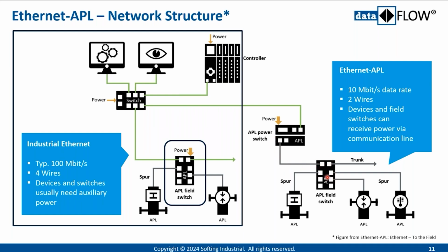The disadvantage with this one is here we're already having only 10 megabits per second. So it means if you have 10 megabits here, all the 8 to 24 or 16 spurs have also 10 megabits. That might be a little bit challenging in the future.